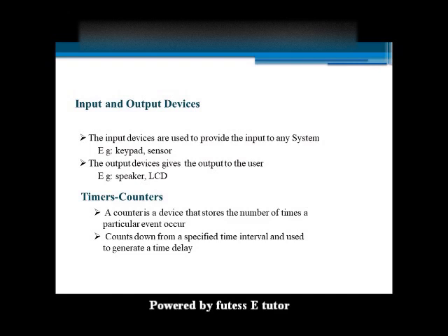For such kind of application where we need a delay for a specific time interval without affecting the normal code execution, we use timer and counter. By setting some registers for timer and counter using programming, we get the desired delay. The amount of delay depends on the system frequency and crystal oscillator.